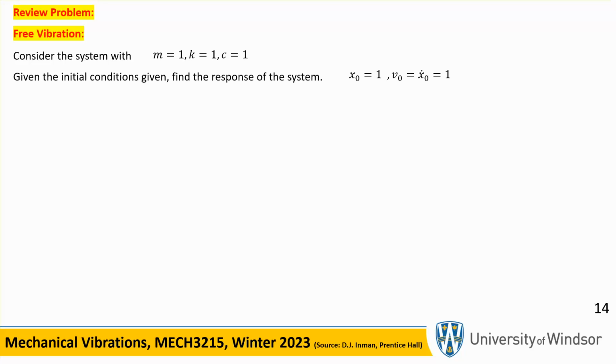However, these are not going to go away. Things are connected. Many things are connected throughout this course, fortunately or unfortunately. You are asked to find the response of this. Well, you go back to your notes or the lecture, and you'll find out, first of all, this is a damped free vibration. I need omega n, I need zeta, I need omega d, and whenever we have a free vibration, there is a formula which depends on x naught and v naught. Of course, you need this intermediate stuff.